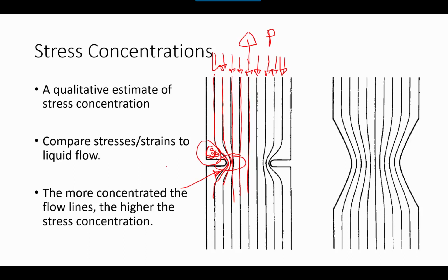And we would also expect, since there's this stagnant zone here in this corner, that this would be a location where stresses are extremely low, because there is no reason for the force to really flow in that region, right? So if we look at this particular specimen, we can see, hey, there seems to be a fairly sharp concentration at these two U-shaped notches, right?